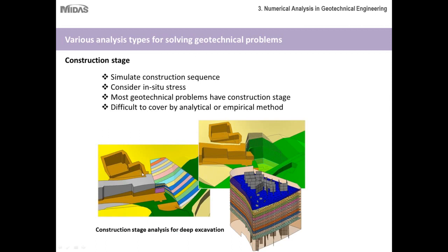So we'll go into more detail about this particular project during the final section of this lecture. But one of the great advantages of a construction stage analysis is that you can take a large, complex, lengthy project and simplify it by dividing it into a number of time-dependent sections. So with this particular project, the excavation was divided into a series of segments, and for each series of segments, a construction stage was created to view how over time the excavation would